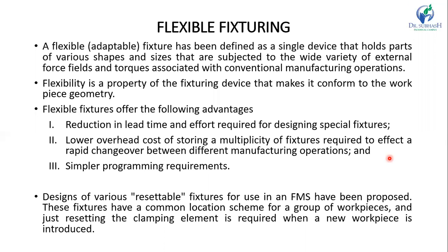And last is the flexible fixturing. So a flexible or adaptable fixture has been defined as a single device that holds parts of various shapes and sizes that are subjected to the wide variety of external forces, fields, and torques associated with the conventional manufacturing operations. So the flexibility is a property of the fixturing device that makes it conform to the workpiece geometry.